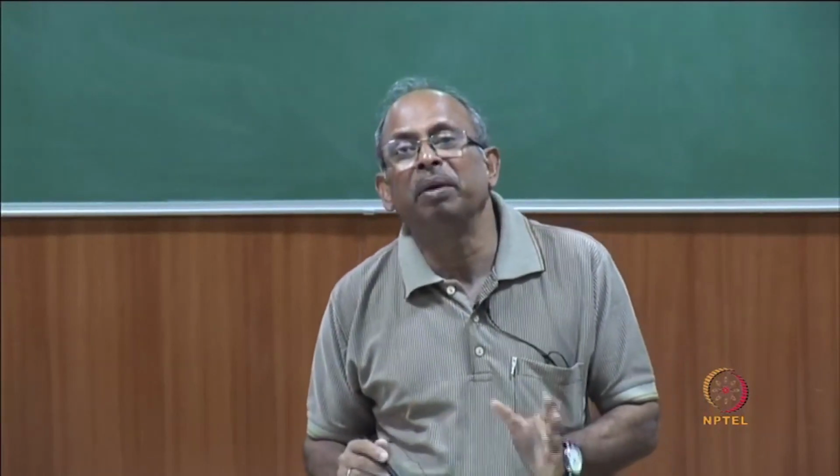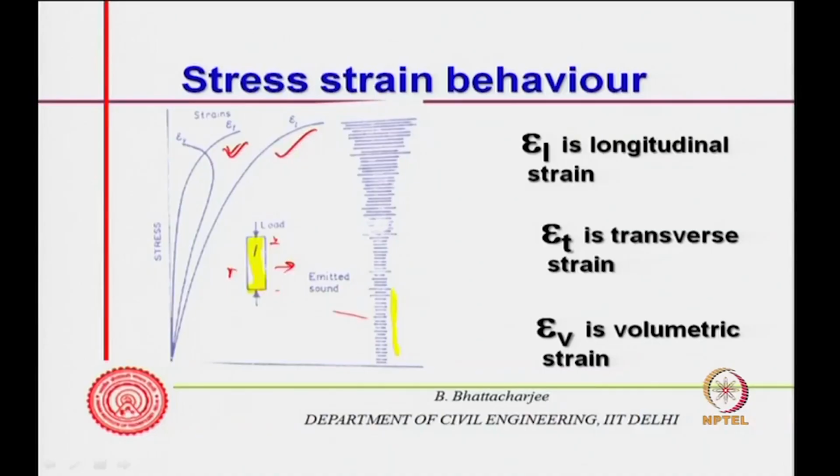In a systematic manner, one can actually trace this. As I apply the load, as I increase the load, initially the emitted sound is very, very little, and it goes on increasing. The emitted sound becomes more as the loading progresses. In other words, permanent deformations and non-linearity are related to a lot of cracking, and this is confirmed by ultrasonic pulse velocity also, sonic pulse velocity.